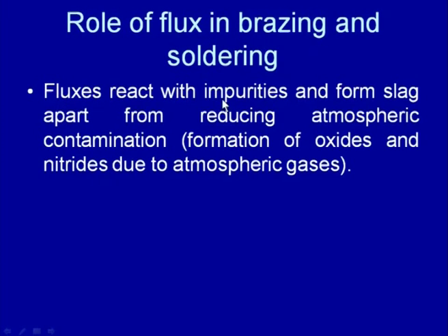These fluxes react with the impurities and form slag during the operation, reducing atmospheric contamination and the formation of oxides and nitrides due to atmospheric gases. When the fluxes are present, they react with the impurities present in the molten metal and form slag.